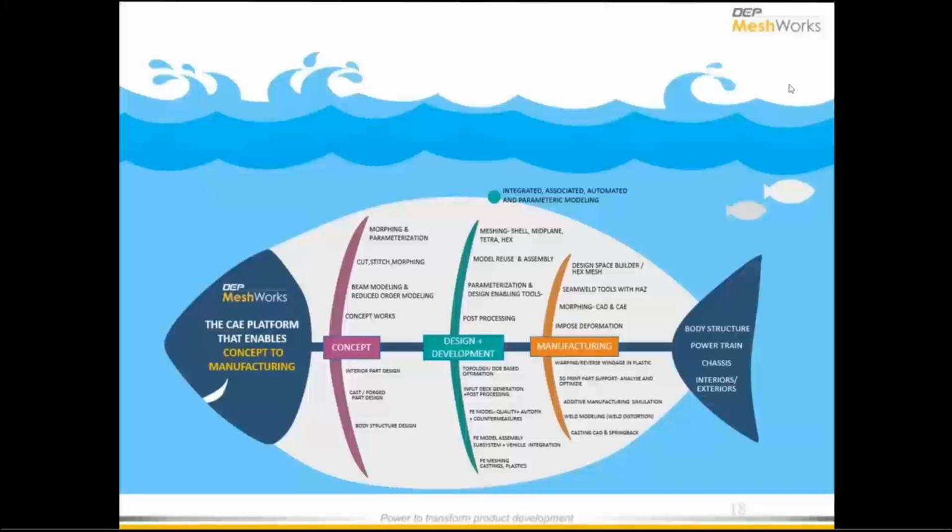Also, the other question is, is it only a CAE model builder? Does it have any modeling tools for CFD? Absolutely, yes. This is a platform, though today you saw only the modeling demonstrations, which were more catering to structure models. But absolutely, yes, for CFD modeling we also have certain tool sets, especially for thermal models. That was the question when you saw the engine model. Yes, we do generate very nice skin mesh models, which are input for your polygonal mesh generation in a CFD application. So those were some of the answers that we wanted to share with you.